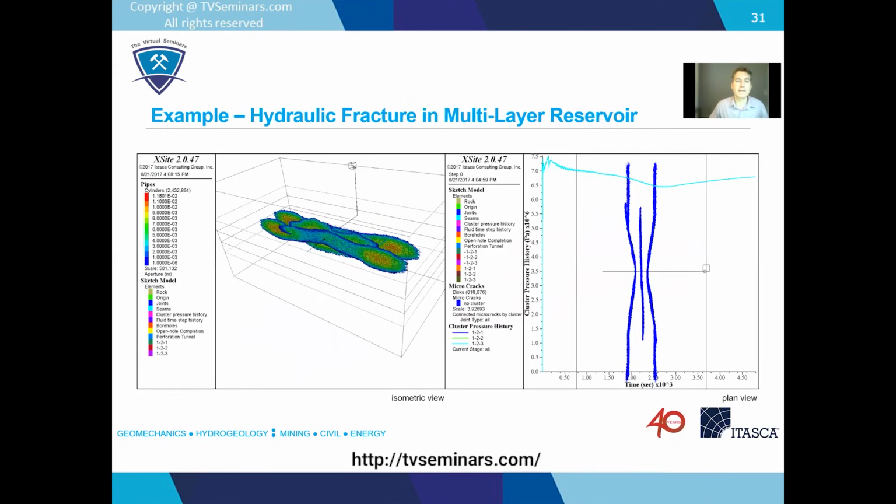Here's an example of that. We use this approach for hydraulic fracturing. That's a program called Explicit. You can see here, this is a horizontal well with 3 injection points. And what's interesting here is that you've got these 3 fractures growing, but there's stress shadowing and interactions between these fractures. So you don't get these perfectly planar fractures. You get some interesting shapes going on here. And in fact, termination of this guy in the middle here because of the stress effects. And so for these kinds of things, you really need a discontinuum model to consider these types of non-planar propagations.